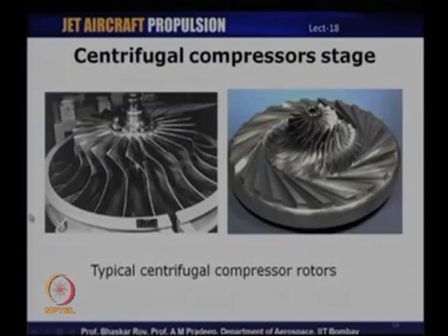So, I will show you those pictures which I had shown initially, just to show you the inducer part of the impeller. For this rotor, this part of the impeller is the inducer. You can see that the flow which is coming in axially will be guided smoothly into the impeller. If there is no inducer, there are chances that the flow might enter the impeller at very high incidences, leading to separation and noise. Similarly, for this rotor, this part of the impeller basically constitutes the inducer.